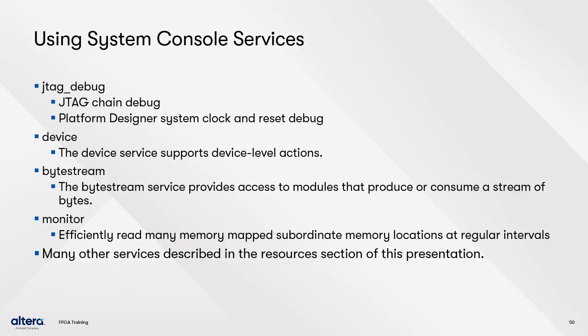System Console services provide access to hardware modules that you instantiate in your FPGA. Services vary in the type of debug access they provide. The JTAG debug service allows you to check the state of clocks and resets within your design.